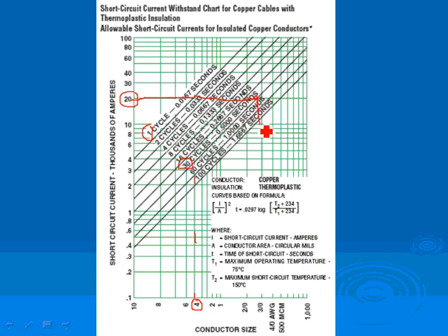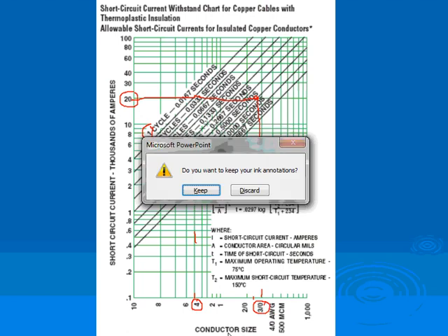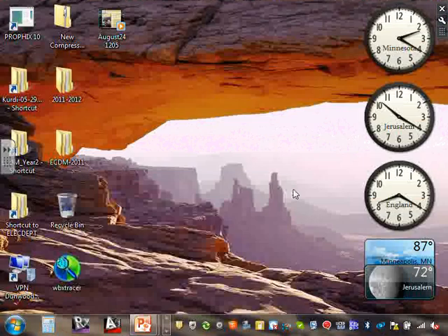Now if you guys go down here, so we're close to this, we're somewhere between 2-aught and 3-aught. So what do you think you're going to do? 3-aught. So the size of my conductor has jumped overnight from number 4 to 3-aught, depending upon how fast I can crank my circuit breaker to trip. That's the concept of sizing for thermal damage. They call it thermal damage. The thermal damage capability. Let me show you one example that I did calculation here based on thermal damage.